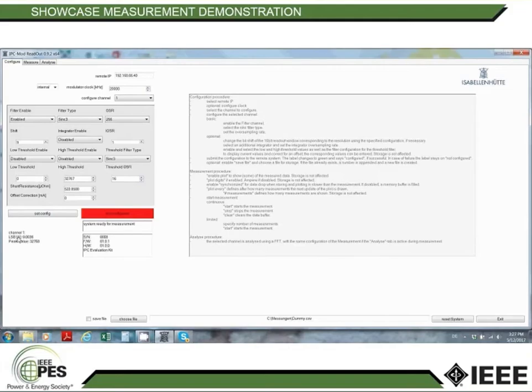The digit size in amps can be seen down here. It is 0.0036 amps. The max value is 32,768 digits plus minus, which equals a 16-bit resolution. If you multiply that, you will see that the maximum range here will be plus minus, I think, around 120 amps. But as said, the whole thing is a test setup here.